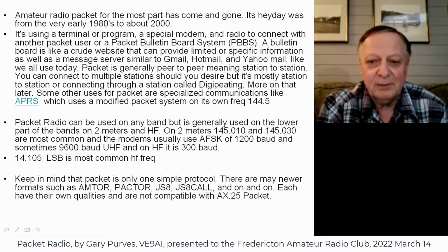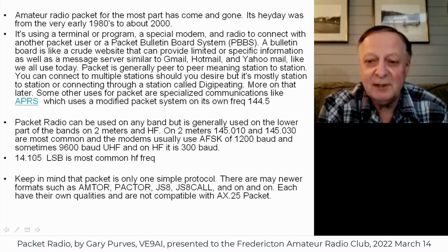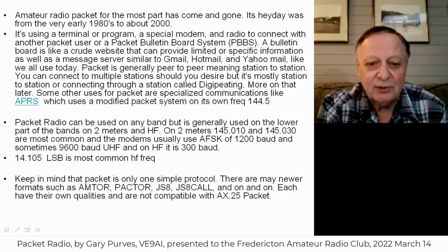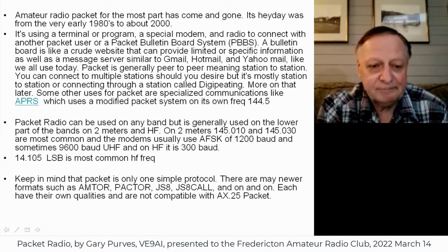Packet is generally peer-to-peer, meaning station to station, but you can connect to multiple stations should you desire. We used to have packet meetings at one time way back on the air, but it's mostly station to station or connecting through a station, called digipeating. More on that in a bit. Some of the other uses for packet are specialized communications like APRS, which uses a modified packet system on its own frequency of 144.5. They modified the AX25 and the programs to work similarly to packet.